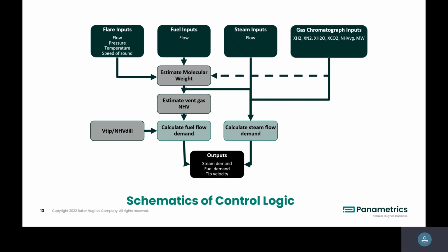Yes, but of course in the US, because of the MACT rules, every refinery is required to have a GC or mass spec or calorimeter. So you can use Flare.IQ for control, and use the GC or mass spec for reporting.